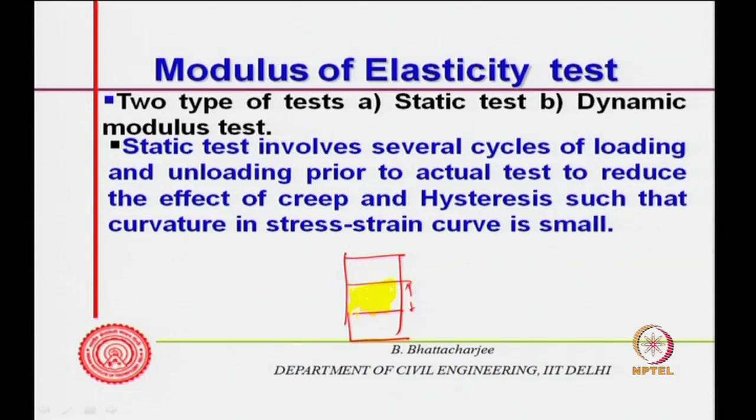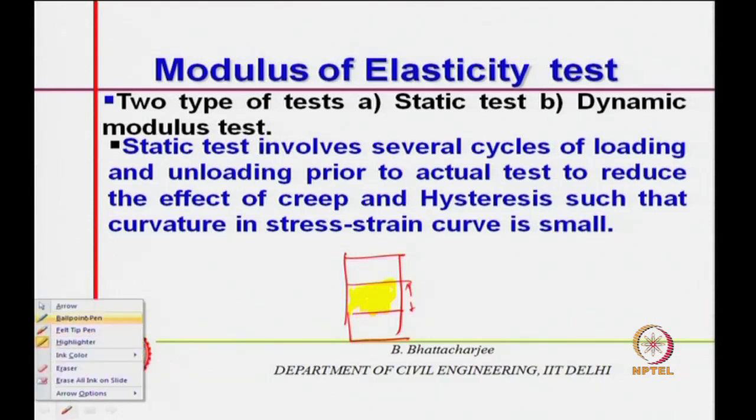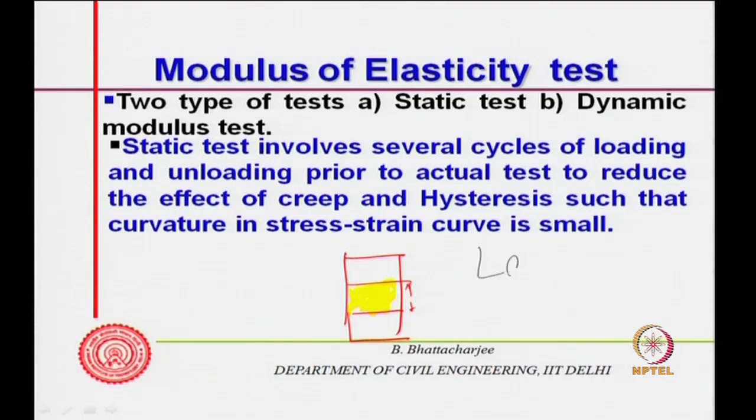So, you put gauges there. In good old days we had Lamb's extensometer, and that is what we were using. We put the gauge in the central portion, so in the 300 mm cylinder, the central 150 mm.